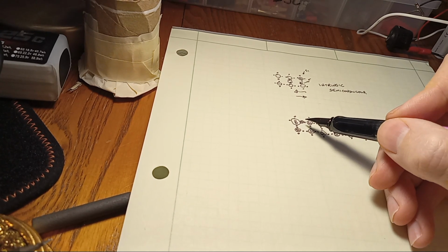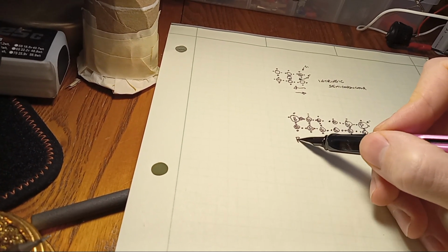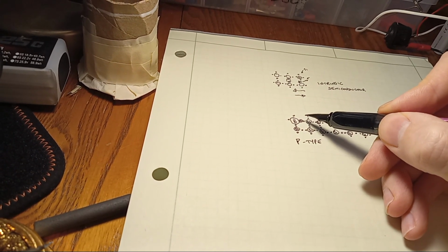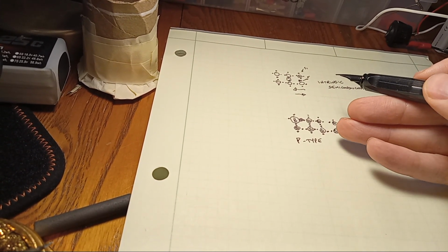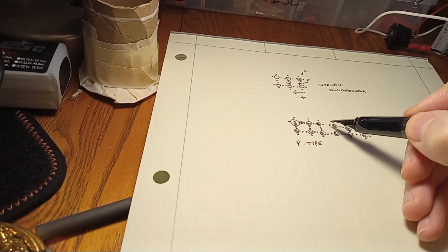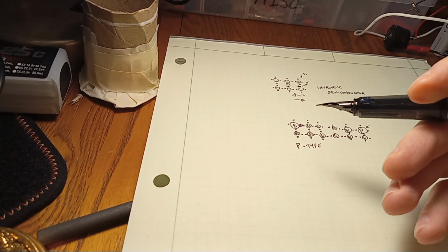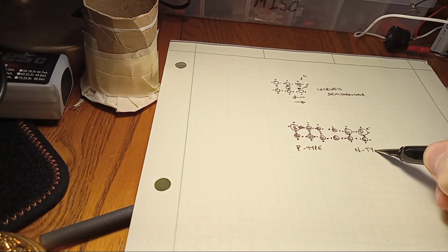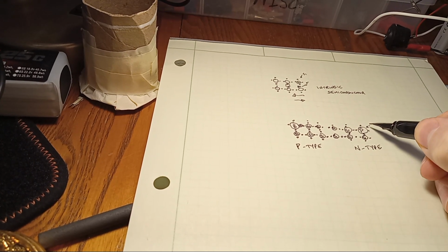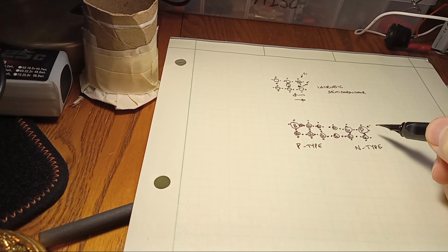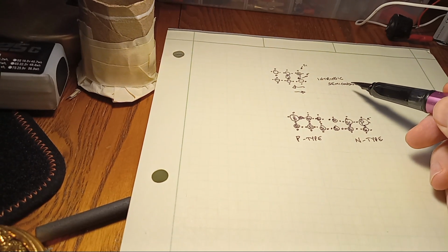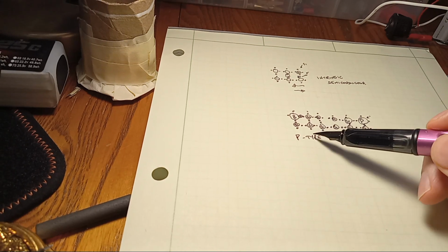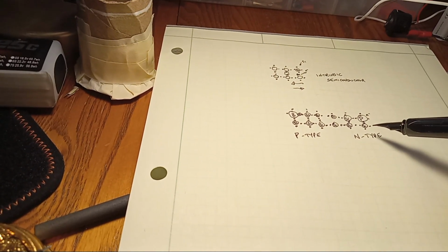The one that has boron is called p-type silicon. It has holes in the number of electrons that should be in the crystal matrix, and these holes can move around, which means that it has a current carrying medium. Likewise, the n-type semiconductor has extra electrons, which can also be moved around. So, while intrinsic semiconductor is a poor conductor unless you heat it enough to jostle these electrons free, p-type semiconductor and n-type semiconductor will both conduct reasonably well at room temperature.